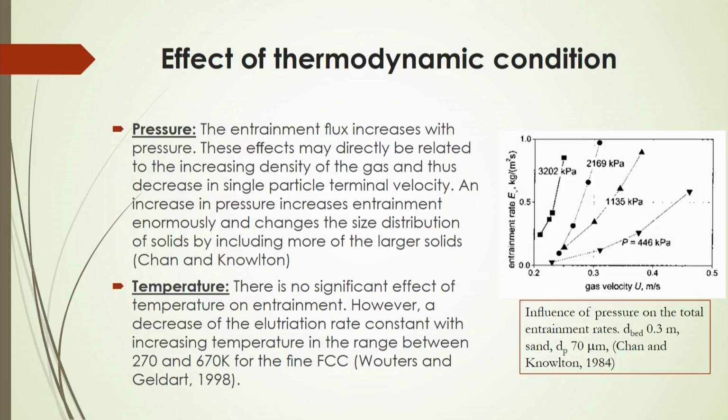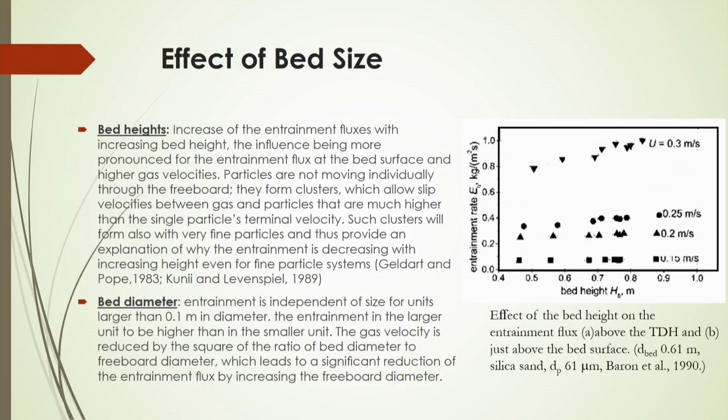So, here we have seen that pressure has an effect on entrainment. Increasing the pressure, entrainment will be more. Effect of bed size: here you will see an increase of the entrainment fluxes with increasing bed height, the influence being more pronounced for the entrainment flux at the bed surface and higher gas velocities.